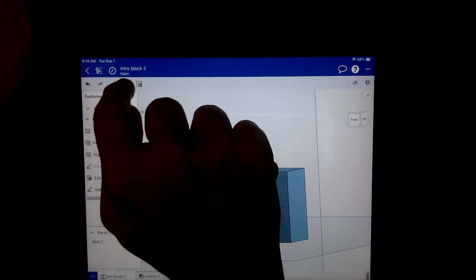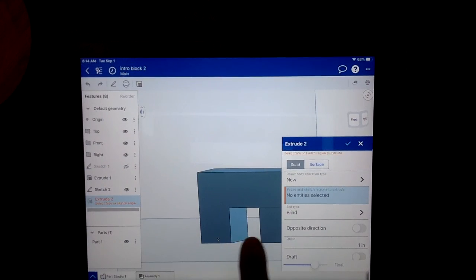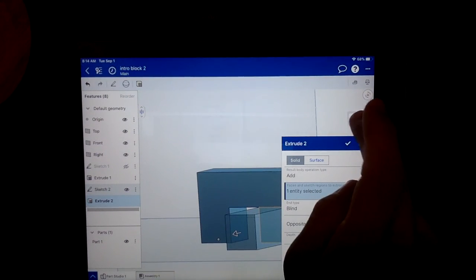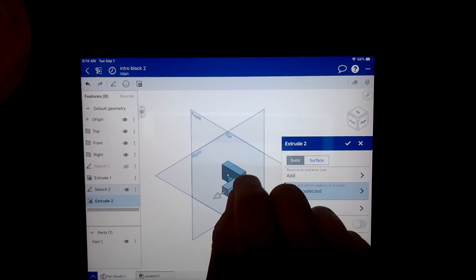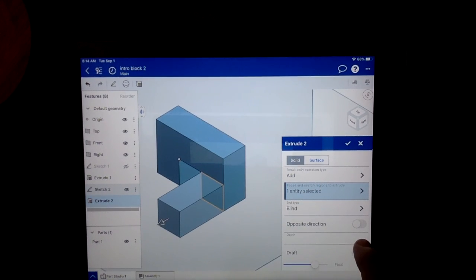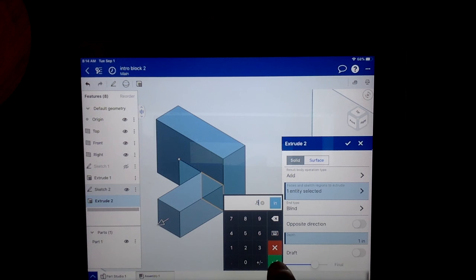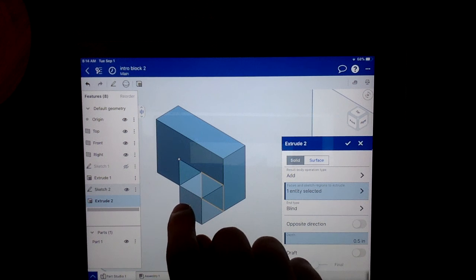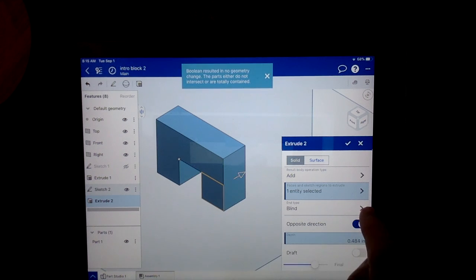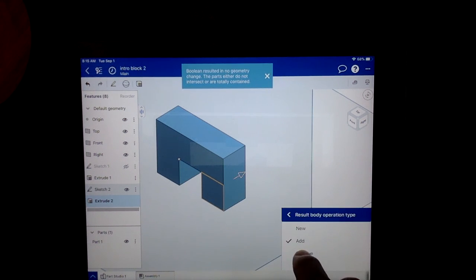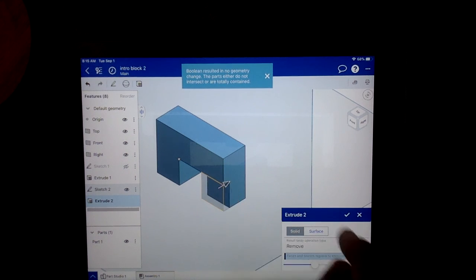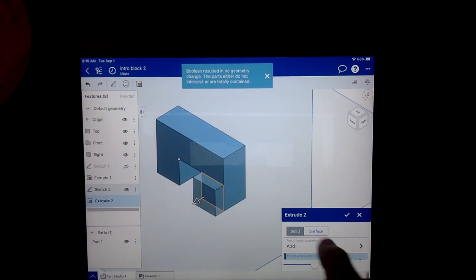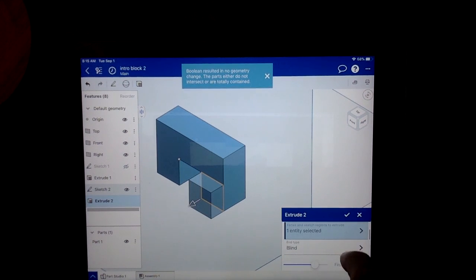And now because I've got those edges defined, I can extrude again. And this time, just clicking on that box. Let me look at my isometric view real quick. There we go. So you can see how that one bit's coming out. So I'm going to change this to 0.5 inches. Just like that. Now remember too, extrude can actually go backwards as well. You can use this instead of as an add, you can call it a remove, and you can cut in your shape if you wanted to. We're not doing that though in this case. We are adding, and we are bringing it out 1/2 inch.